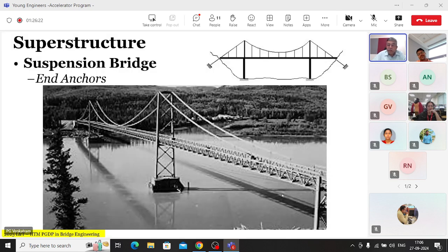Okay, so we have gone through the whole gamut of superstructure, from bending plus torsion, to axial tension and axial compression. Then we are going to pure axial. Then we are going to the deck, significantly with pure tension. Of course, in the deck member there is some bending, but it is much smaller, with the spacing of the suspenders. So we practically call it a non-bending element, and the stiffness that we provide for it. Okay, so now that's how we have seen a whole spectrum.